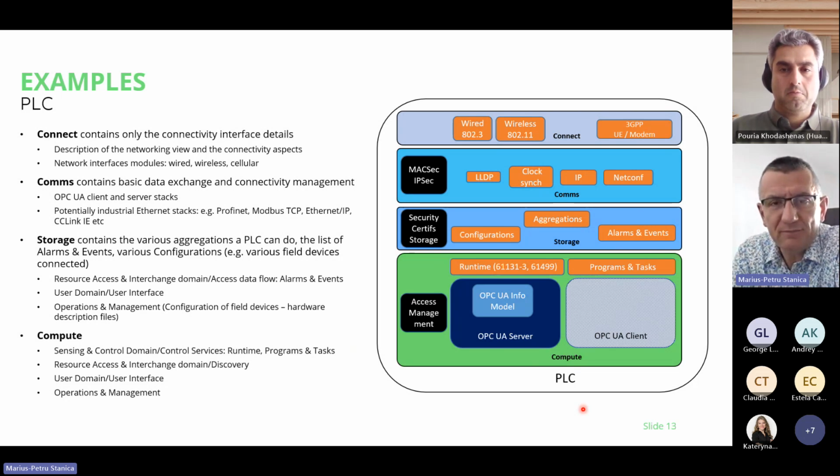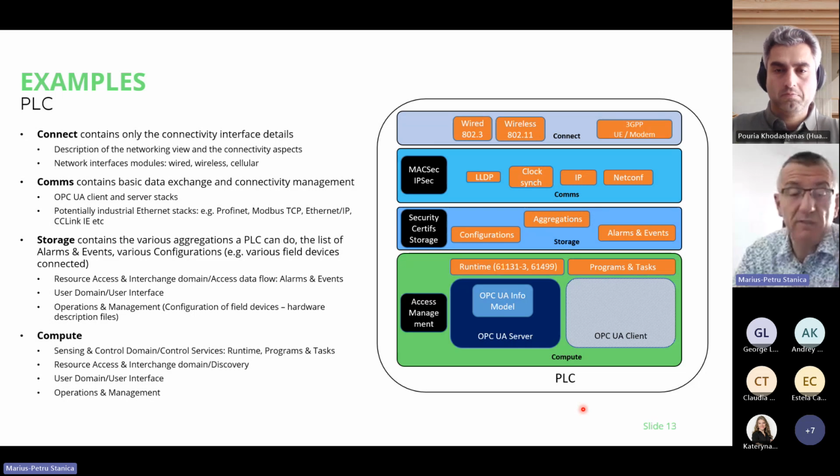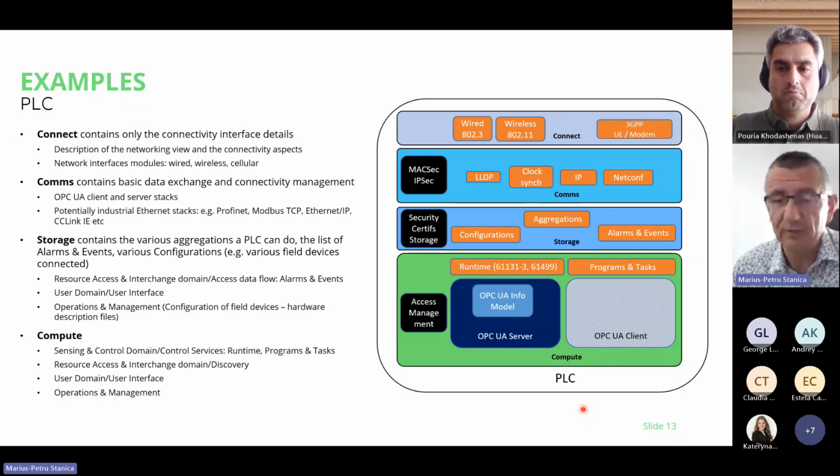But next to that, you may have existing field buses. Field buses allow you to exchange data between systems in older, legacy manners, which are still ongoing, still functional, and may still run in parallel to OPC-UA. Currently, OPC-UA is being developed, it is not so developed yet, but now we are developing it to the field level. Before, those field buses were covering exactly that field level. So most of our projects run on field buses because this is something which is currently fully defined.